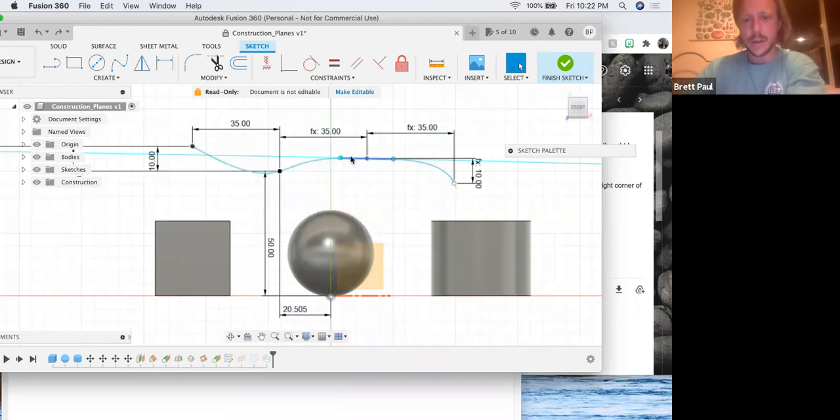So the reason it gave me an over constraint there is I located this thing in space horizontally, or in the x-axis, if you will, and then I've already defined each of these other points with respect to one another in the x-axis. So I don't need to go back and define the dimension with respect to the origin, at least horizontally.